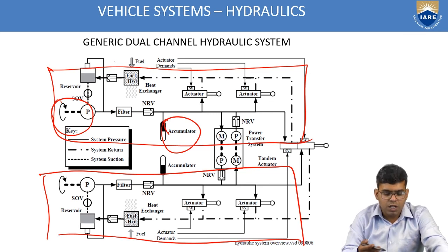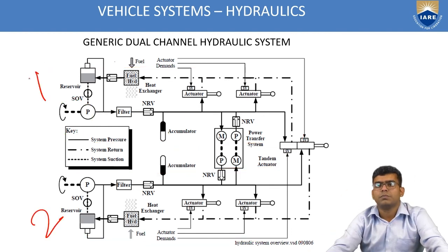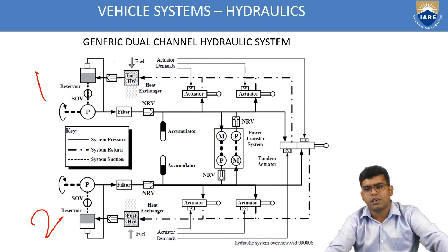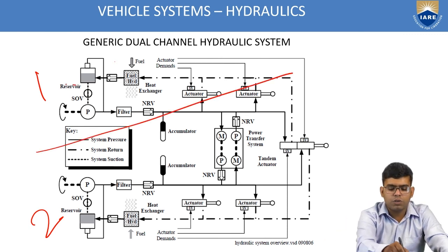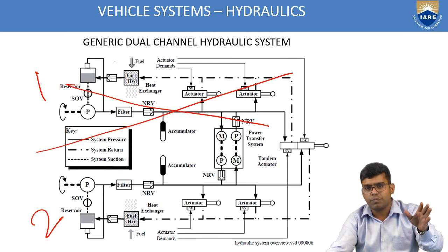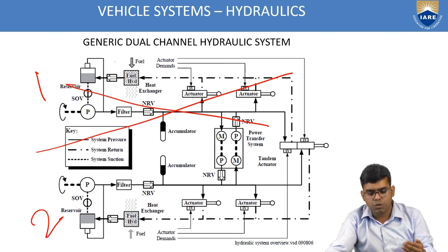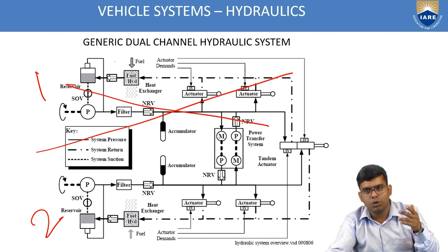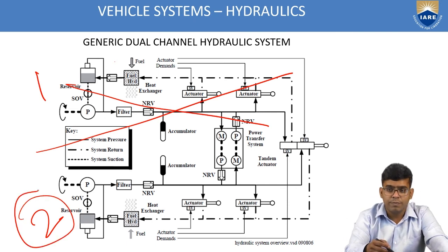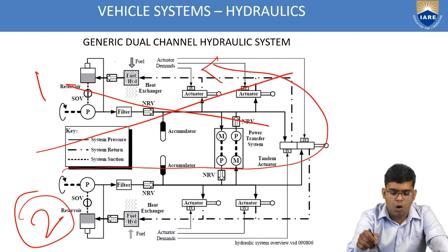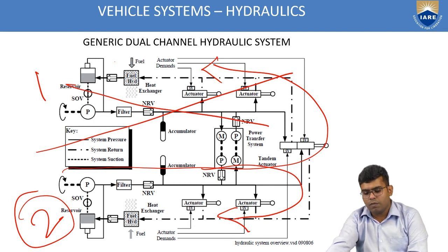Let's say that my system 1 has failed due to some issues with the in-flight conditions. I cannot use this system. If I have only one hydraulic system, my aircraft cannot fly; I cannot operate it. That is the reason why it is always better to have a redundant system with 2 or 3 replicas of the same identical principal system. In that case, the second system kicks in and passes the hydraulic fluid through all the circuit members as per the demand.